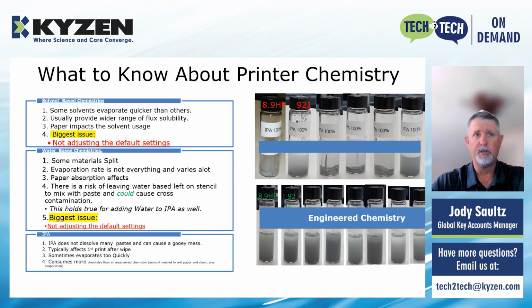If you look at the water-based, some of these chemistries split because they're mixed with water, so most of those are typically run at 15%. There's a different absorption and evaporation rate for these as well, and it varies in some cases. There's also a risk of leaving water on the stencil that could intermix with the paste and cause some cross-contamination. This holds true for water and IPA as well.